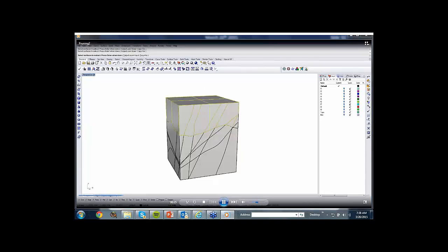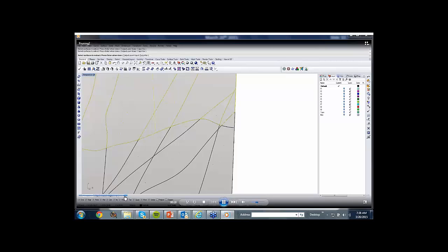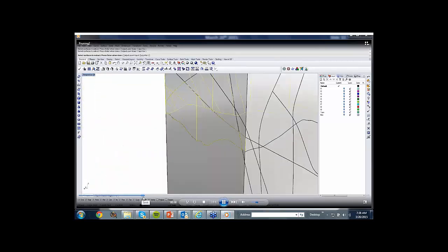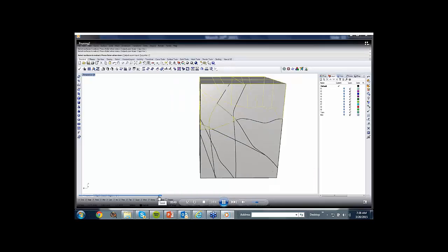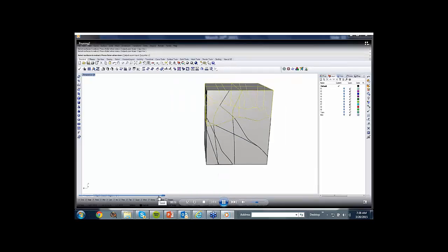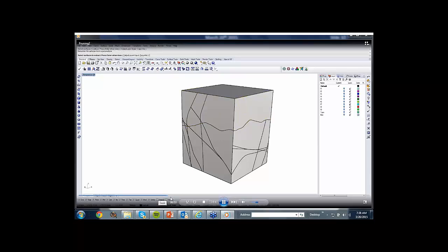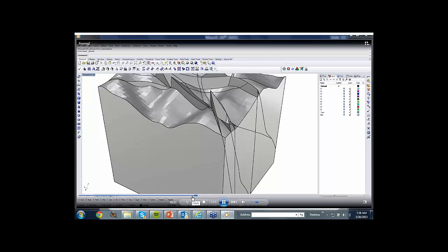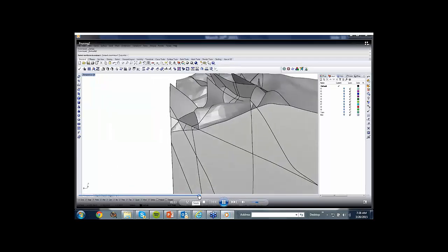I don't want to mesh. I mean, if I wanted to mesh an excavation from the top, I could have. But what I'm doing here is removing these extra surface patches that we have. That non-manifold surface that we had originally remains one single non-manifold surface. So everything I remove still remains a good candidate for KUBRIX, albeit not necessarily practical.